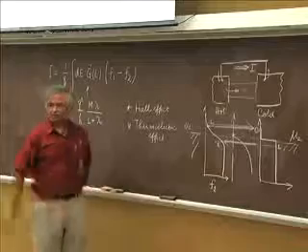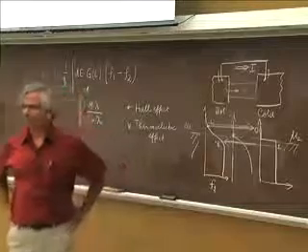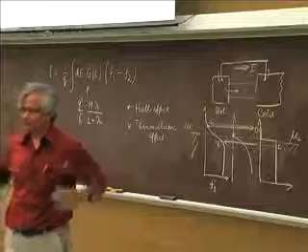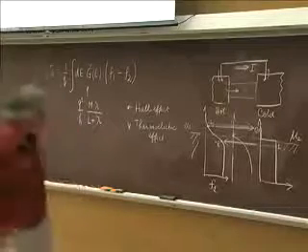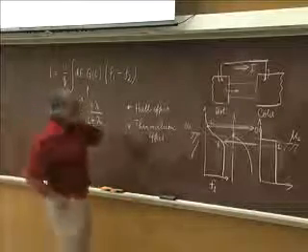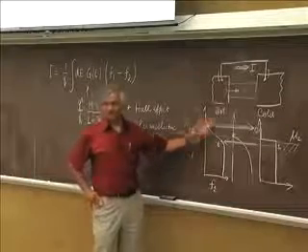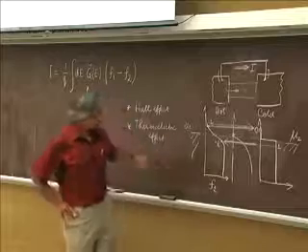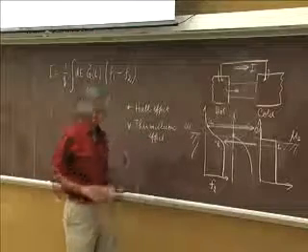These are the two standard ways of telling the difference between N and P, because just from conductivity, you usually can't tell which is which. Now, thermoelectric effect, all I'm saying is it is really all from F1 minus F2. That's it. But for Hall effect, though, there is actually a real difference.